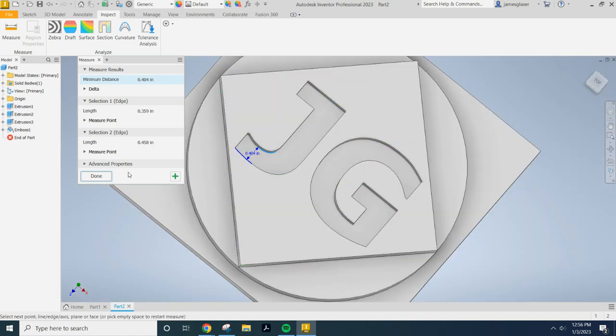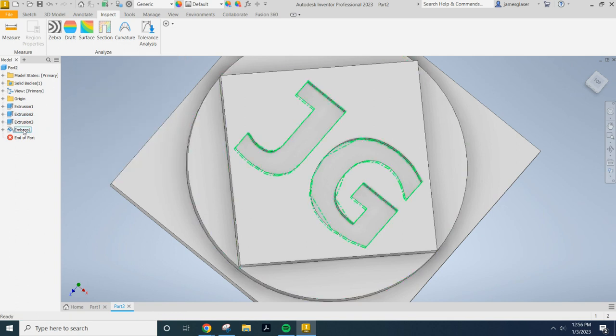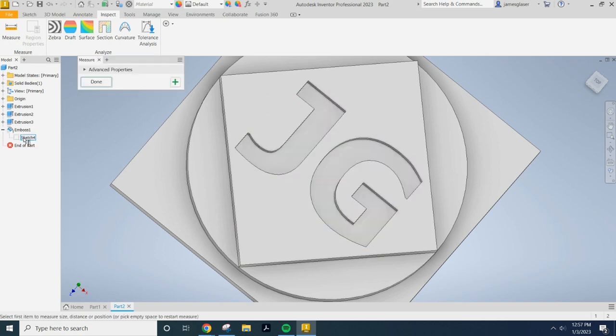Yeah, if you make your letters too narrow, it's not going to work because the drill bit is a 1/4 inch wide. And if you have your letters being like a 1/20th of an inch, that's not going to work. That would be 0.05 inches. So nothing too scrolly. You want something nice and big and blocky. In fact, let me just show you something not working.